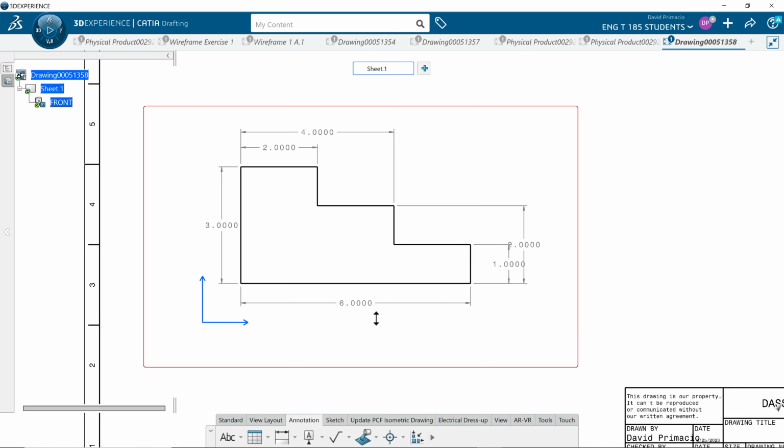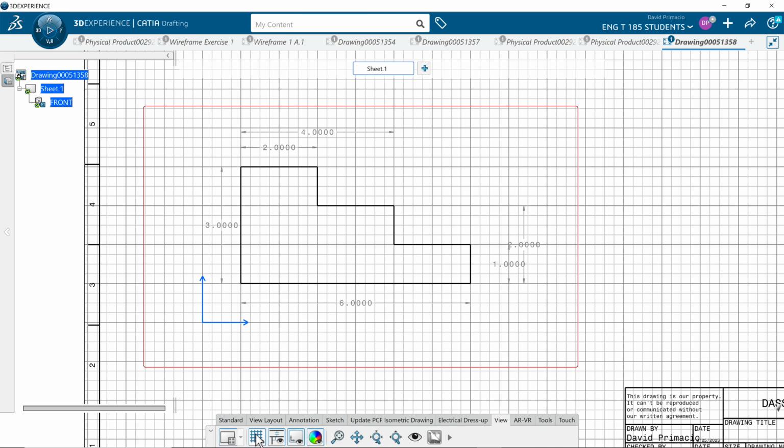And there's your dimensions. Notice this 0 is too close. What I do is I turn on the View tab and turn on the grid. That 0 should be 3/8 to 1/2 inch apart. So if I just move it another 1/4 inch here, this one here looks good. This one looks like it's got enough spacing, but that number 1 is too far. It's barely too far. Maybe I'll move it just a nudge.